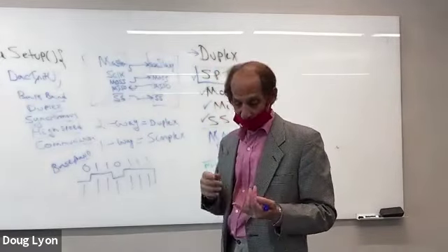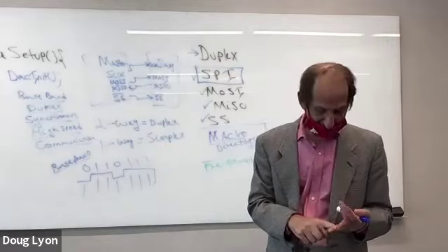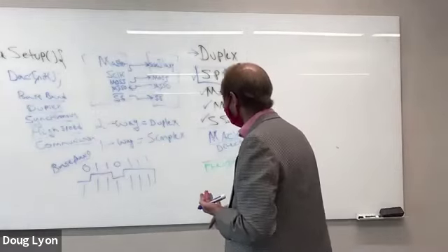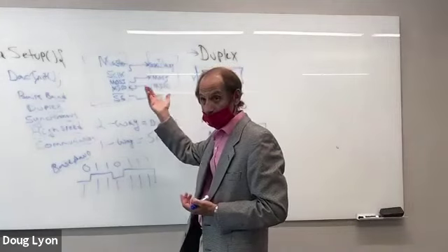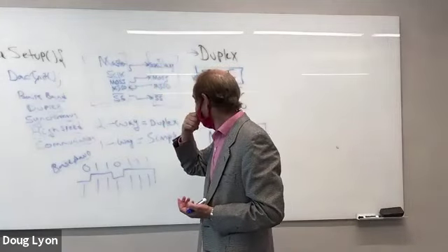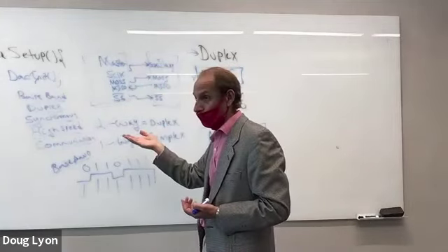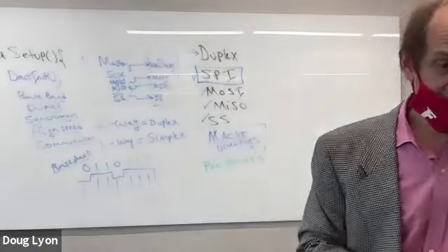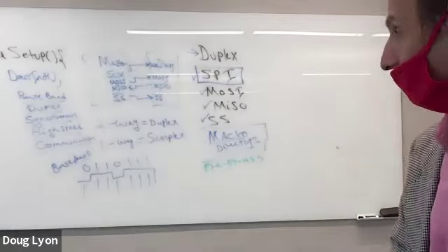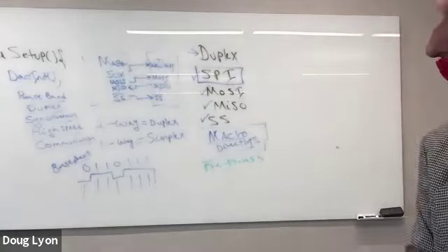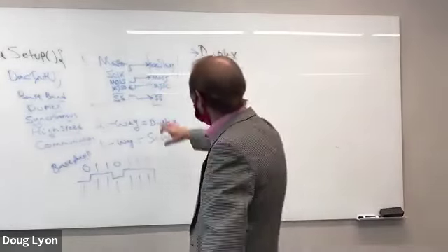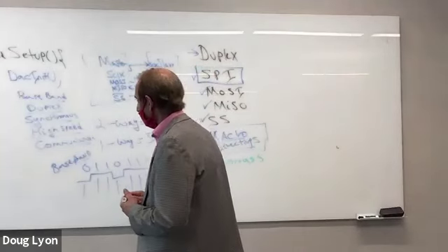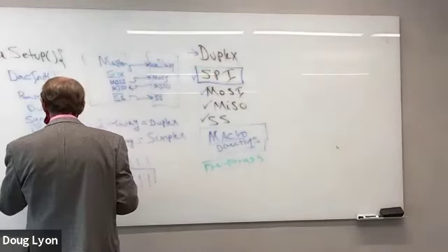We have to know if it's a 10-bit DAC, how fast it goes, what kind of serial clocks we can use, various interesting and wonderful things like how you order the bits in order to get them to come in, whether they come in 1 byte at a time or all 10 bits, if it's a 10-bit DAC, things like this. But in other ways, it's very standardized. So this is what you call physical layer. Right? So this is a baseband duplex synchronous high-speed communication physical layer.